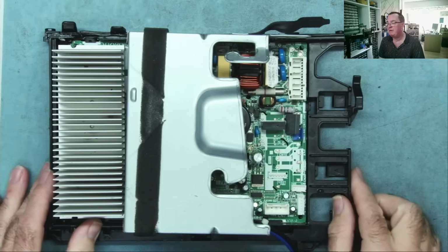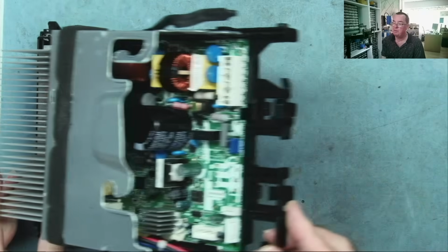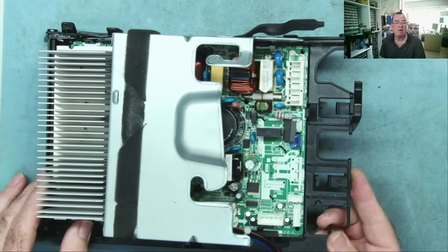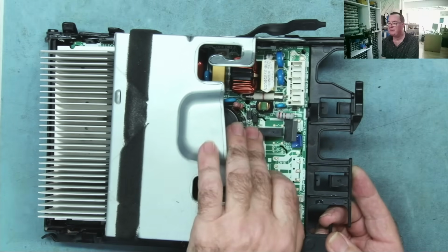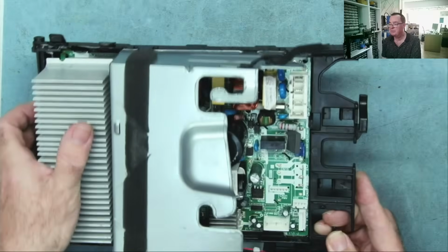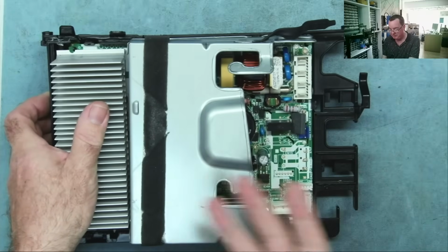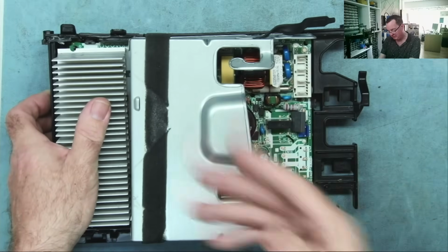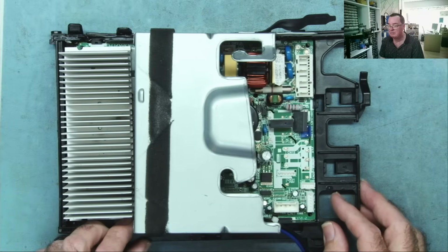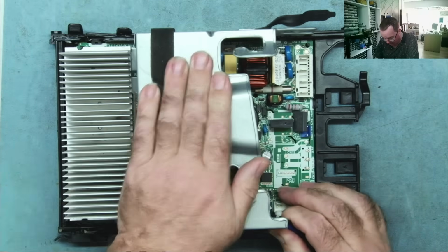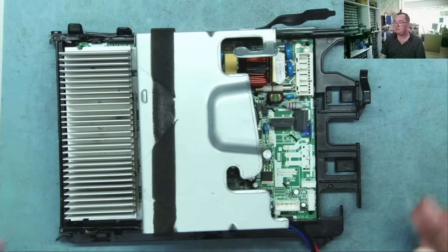This is the PCB from the outdoor unit, the controller board. I'll link to the video I made, but I've basically checked everything on this. I looked at the communication, which are these optical isolators between the two. It basically powers up on the bench. I hear relays clicking, there's LED flashing. Obviously the microcontroller is awake, alive and kicking, but it just doesn't work.